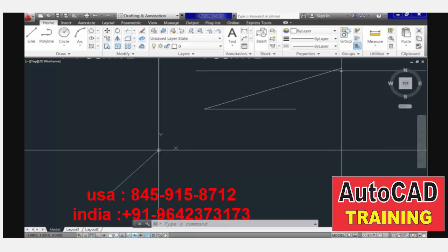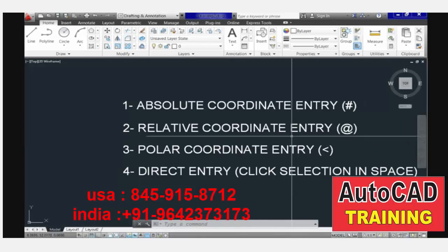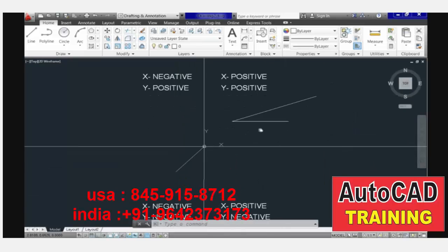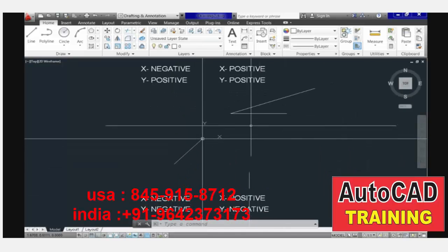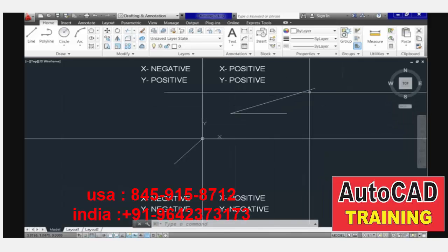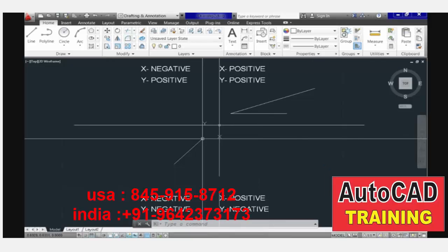In this case, relative is associated with the add symbol, which means that AutoCAD is using the previous point, the last point you selected, as the origin. When you select a different set of numbers, like 0, 2 or 2, 6, the last point is the one you selected.